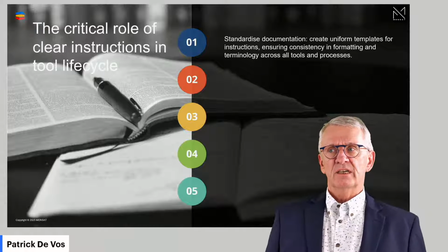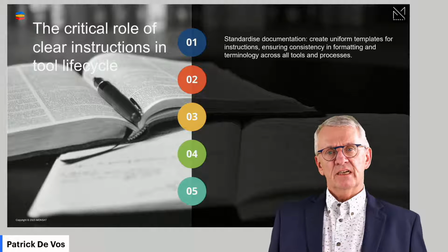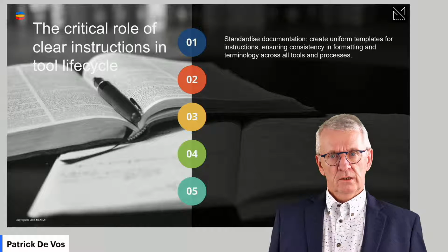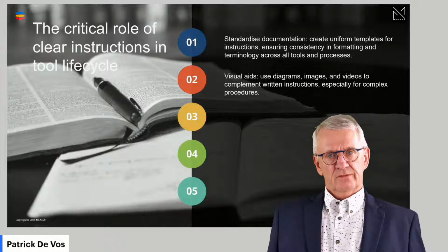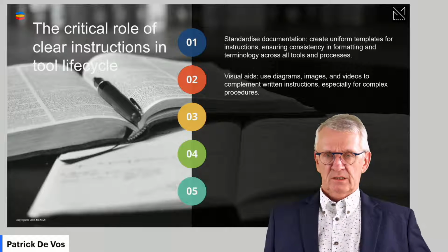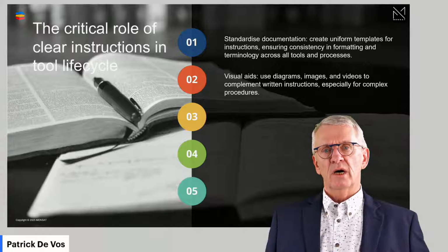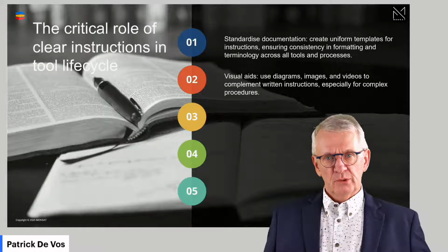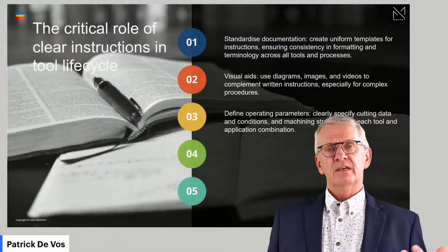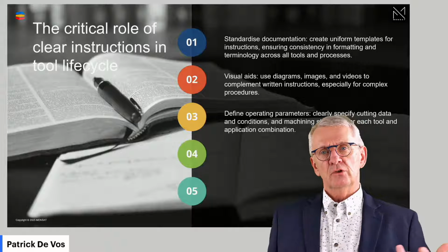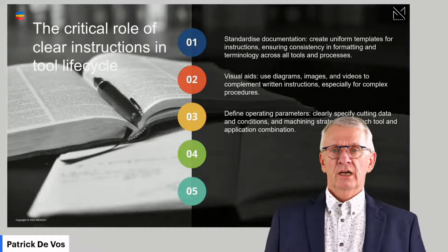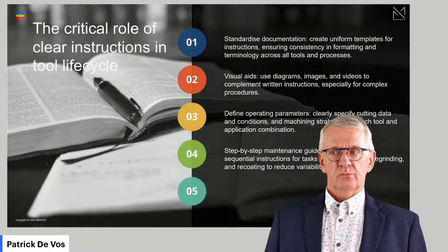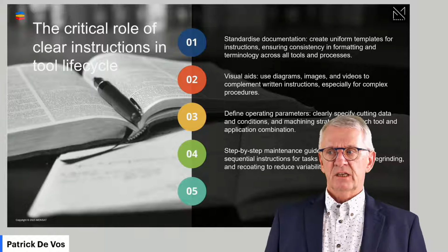And talking about communication channels, there should be a standardized documentation set that everybody can consult to see what and how and when. Possibly use visual aids. I know it's not of this time anymore, but posters are such an interesting thing to help remind people of certain principal things around tooling. Define operating parameters very clearly. Should you use cooling or not? What are the cutting conditions? When do you index an insert?